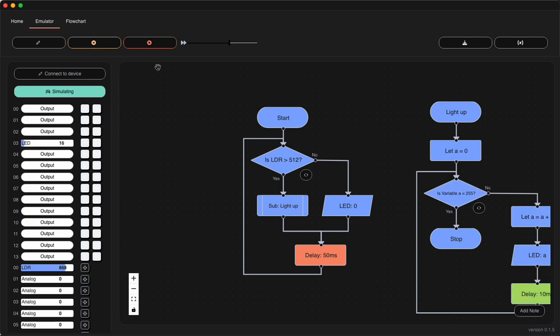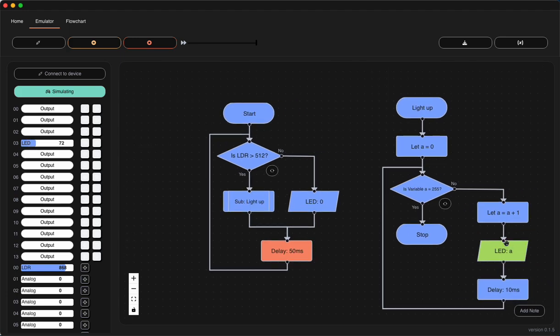We might find that that's a bit slow, but you can see it's starting to go up as we go through, and you could always obviously adjust how fast or how slow that goes by changing that number or changing the delay. But we can see it's running up nice and as we wanted it to, until it gets to 255, and then it's going to stop and jump back out into checking it again.